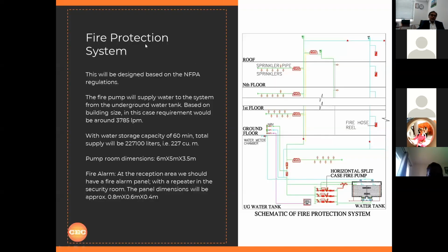Now, this is not a day-to-day utilized system, but this is for life safety and mandated by all the civil defense regulations. The famous standard all over the world is NFPA, which stands for National Fire Protection Association. It is an American standard, worldwide used and followed by most of the countries in the world. Here again, we'll be having a tank in the basement, and with the pumps, it will be distributed to the sprinklers.